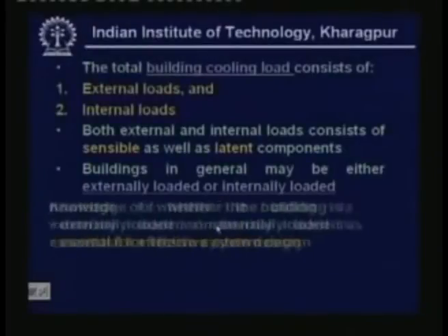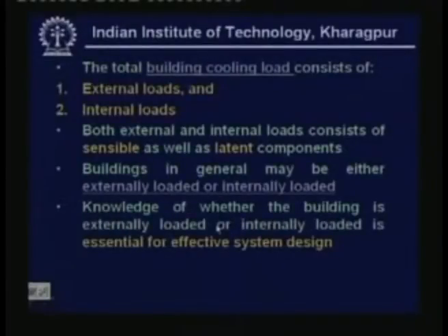So, you find that irrespective of the outside conditions, the load on the building remains more or less constant, which depends upon the occupancy. So, the knowledge of whether the building is externally loaded or internally loaded is essential for effective system design. It helps if we know beforehand whether it is externally loaded or internally loaded.